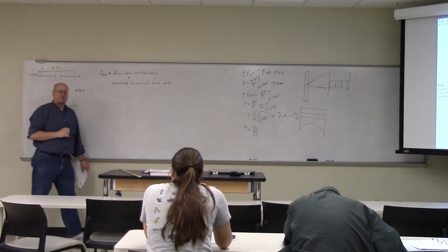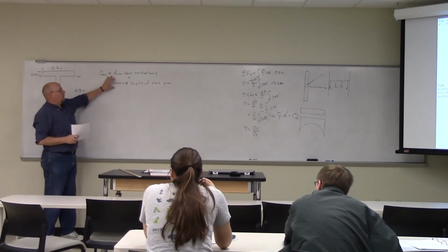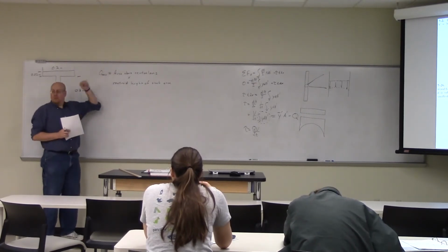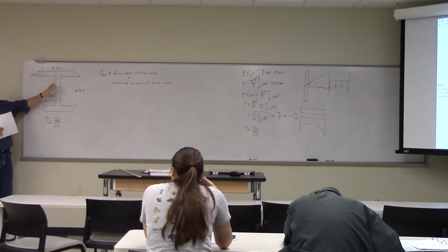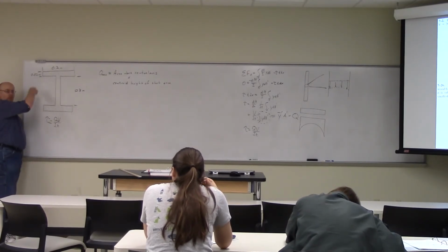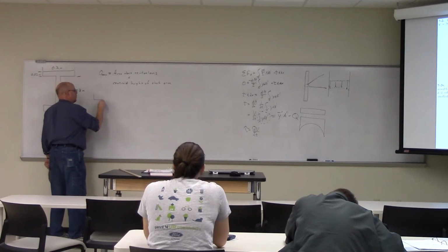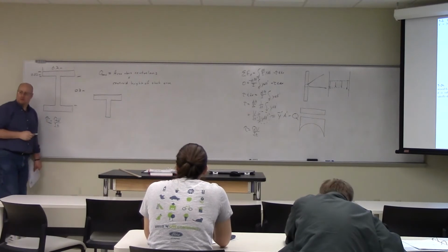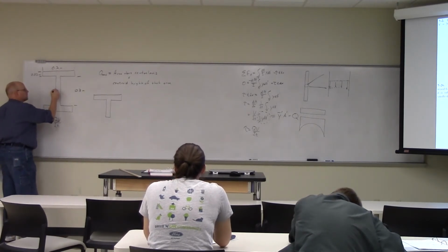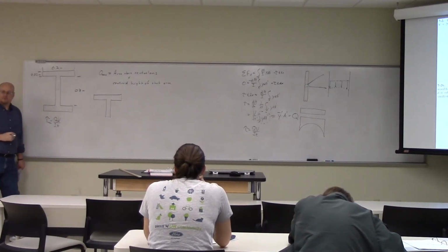Right. So we just said the area above the neutral axis times the centroid height of that area above the neutral axis. So really, the thing we want to describe here is twofold. We have to have the whole shape to get I. But then for Q, we're interested in just that piece, which would be the area directly above the neutral axis.